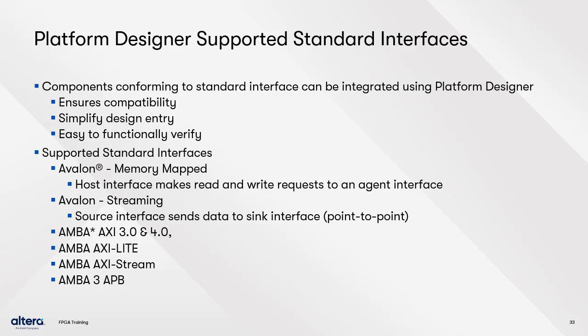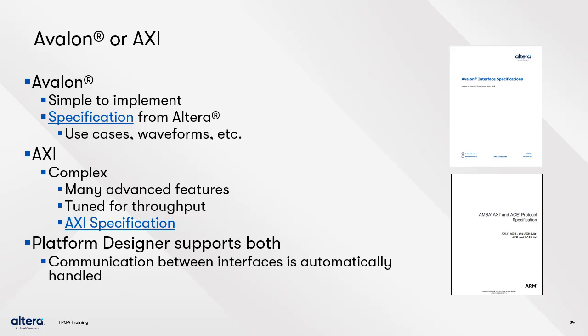If your custom component conforms to one of these standards, your component can be seamlessly integrated with other IP by the Platform Designer tools. Before conforming to a specific interface standard, it's important to understand the interface completely, and this can be done by reading the specifications published by Altera or ARM.